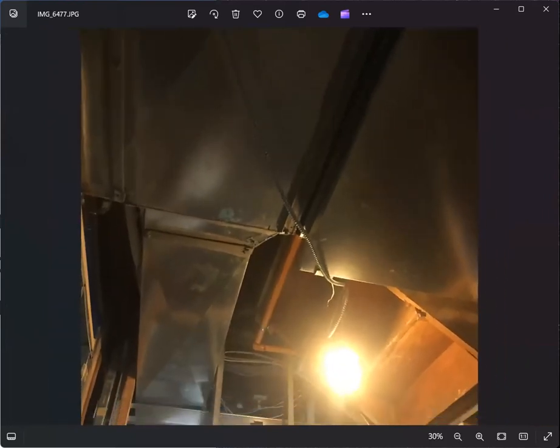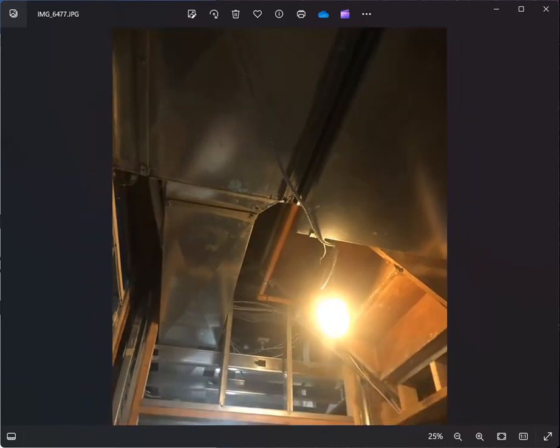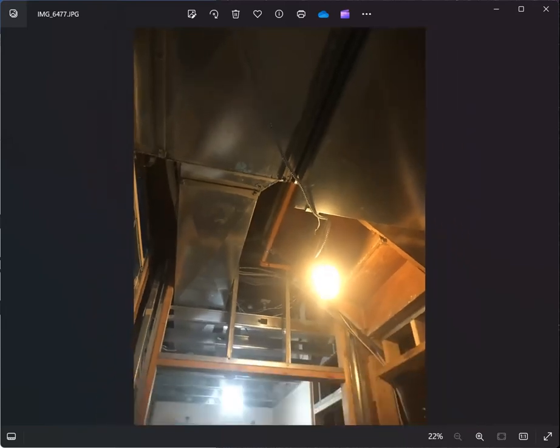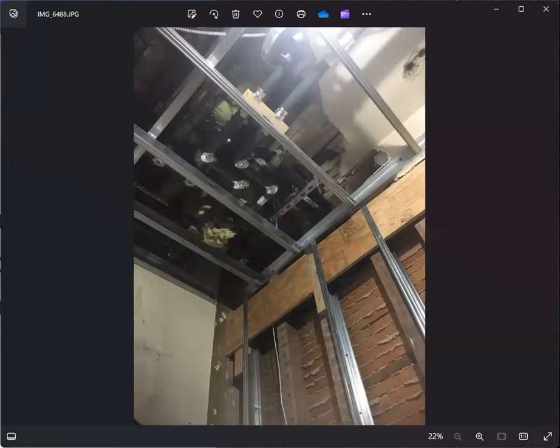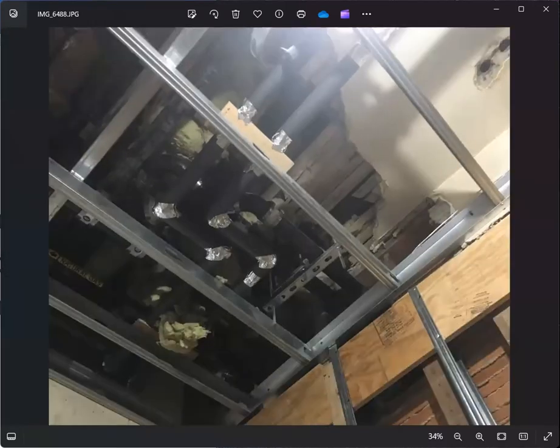This ductwork has particular gauges, so you could probably identify some of it. If you see a sticker on the surface, most likely some of them have stickers, and if it's still on the floor, you could measure the thickness to check if they are using the right gauge for the ductwork.